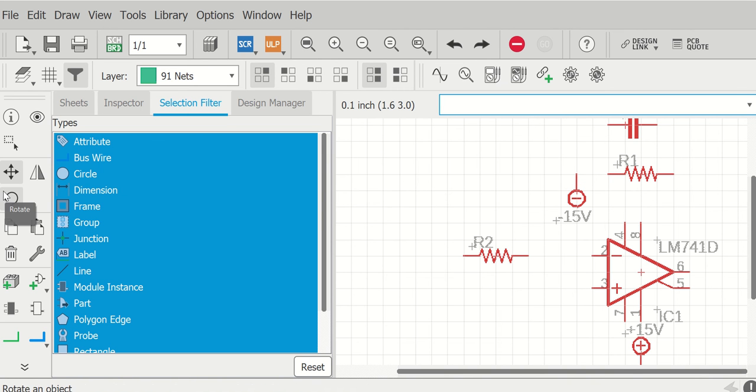And then you can turn that. You go to rotate. You turn it. And then you connect it, then you have to move it. So for each step, you have to go back and choose the right tab. Then you come and connect this to minus, and this plus you have to rotate it. And then you have to move it. So you come to move, and then you go back and you move it and put it there. Okay. So that's for op amp.